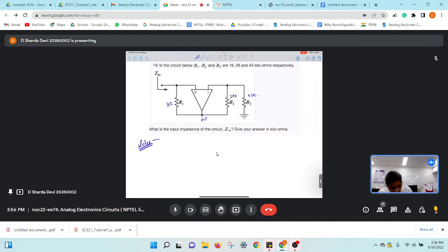So this is the output, right? When output connects to input, what do we call that? Feedback. Yeah, so it's a feedback. And in this particular circuit, you can observe that we have both positive as well as negative feedback. Okay, this is clearly evident, no? Now, since the resistive values are larger in the case of negative feedback, so considering negative feedback to be dominant, what will be the output if you consider the negative feedback to be stronger?